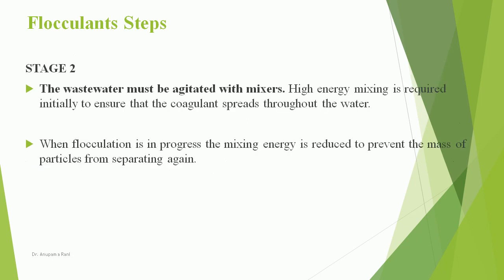Stage 2. The wastewater must be agitated with mixers. High-energy mixing is required initially to ensure that the coagulant spreads throughout the water. When flocculation is in progress, the mixing energy is reduced to prevent the mass of particles from separating again.